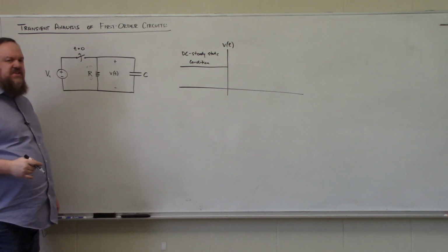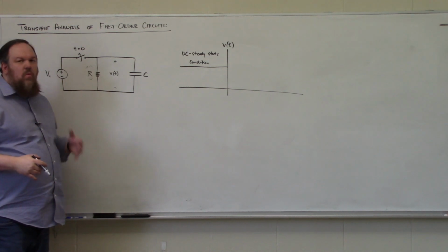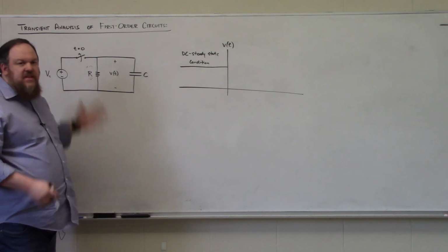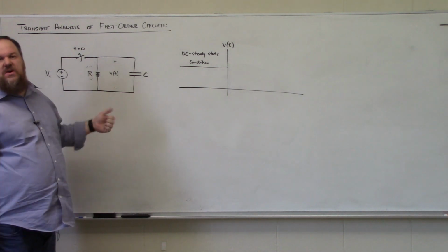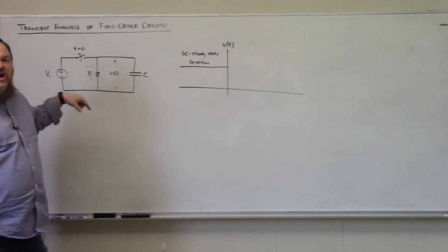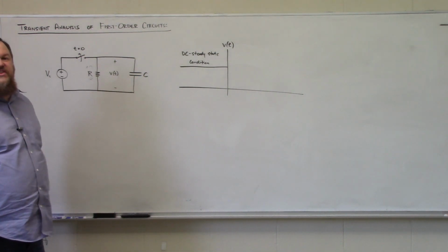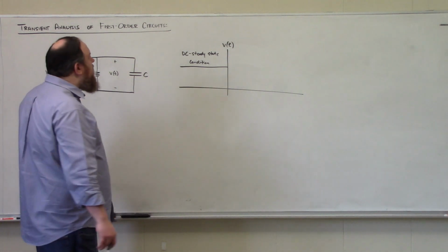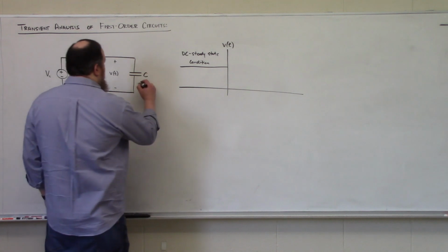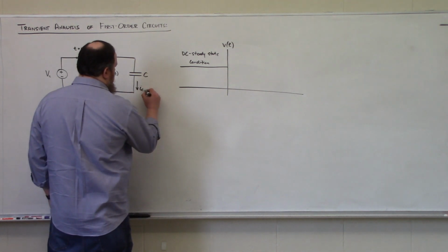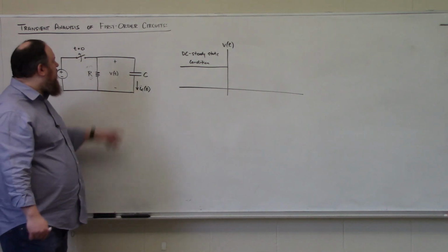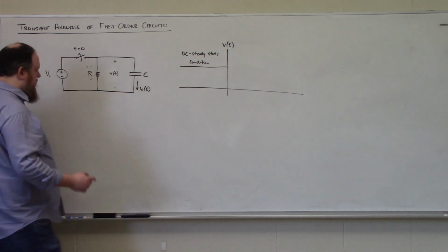After we open the switch up, what should we expect to happen? Well, we're still looking at the voltage drop over a resistor, and we saw that when we interrupted the supply voltage, the voltage drop over the resistor went down to 0 instantaneously. The problem we have with that is if we look at the capacitor current. So I'm going to define my capacitor current to be in this direction, down, so that the current is flowing into the positive polarity terminal.